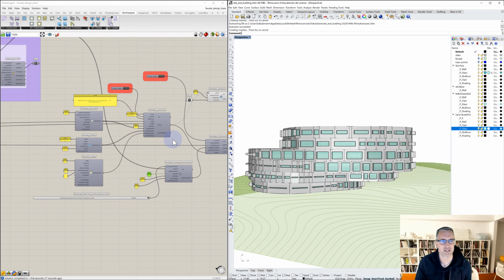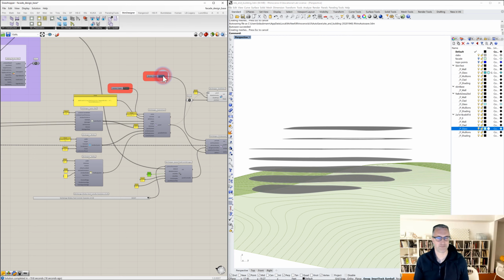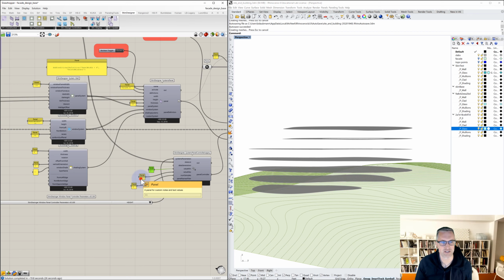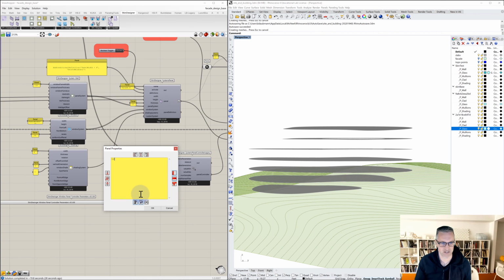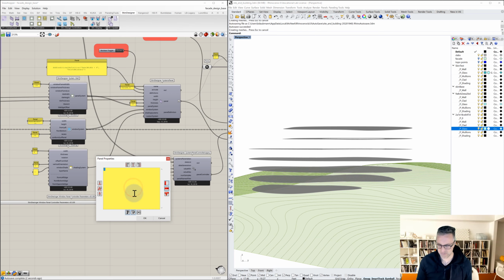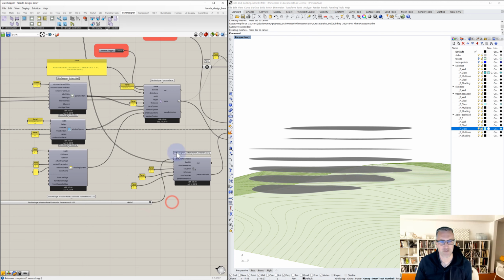But now let's deactivate for a second. And let's set that to be, we know that the overall height is 13. So I'll set this to 12. And then let me set the sample to 2. And I believe what should happen is that we'll either get a 12-foot piece of glass or a 1-foot piece of glass.